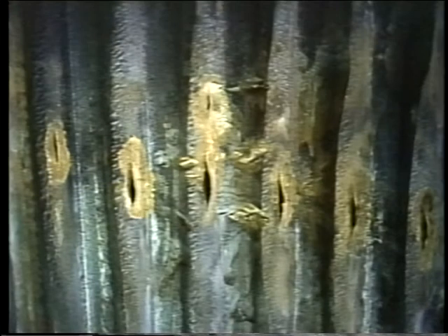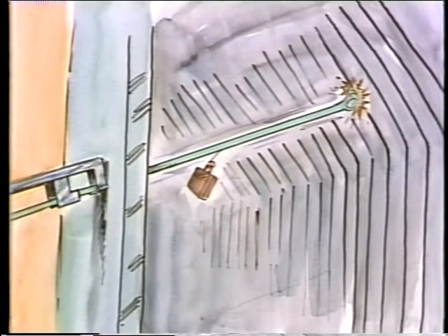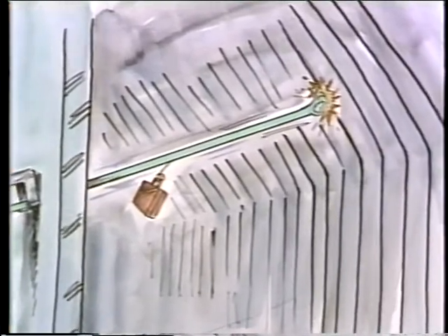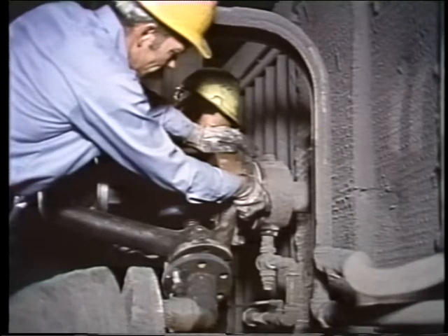Soot blower alignment is not often a problem, but sometimes there may be evidence that a soot blower is misaligned. Soot blower misalignment can cause the blowing medium to blow more strongly over part of the tubes than it should. Eventually, this will erode the tubes enough to cause them to fail. That's one clue to misalignment. Long tube retractable soot blowers that are misaligned may actually run into tubes during their travel. When a soot blower is put into place, it can be aligned by shimming at the boiler wall mounting or on external supports to square it up.